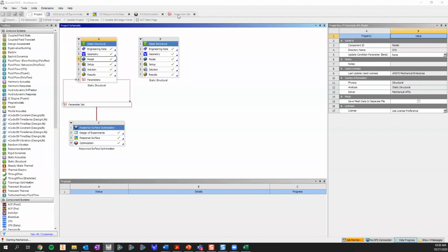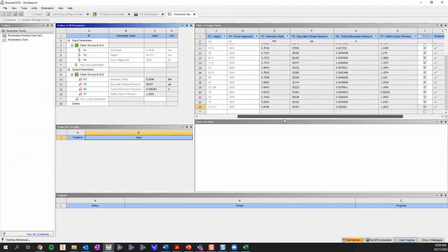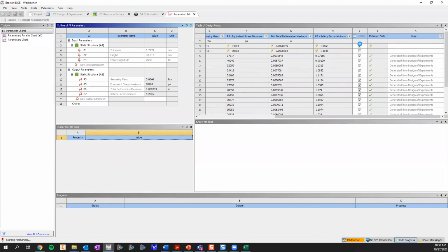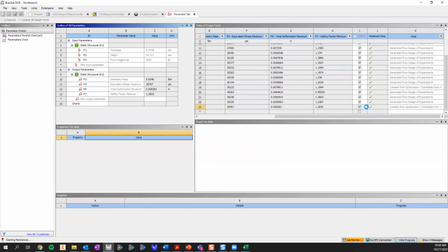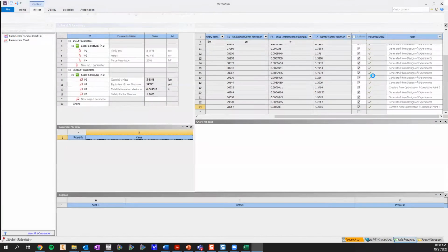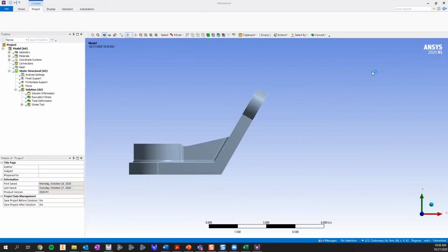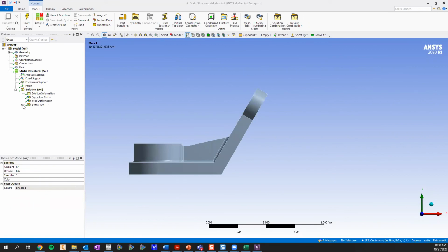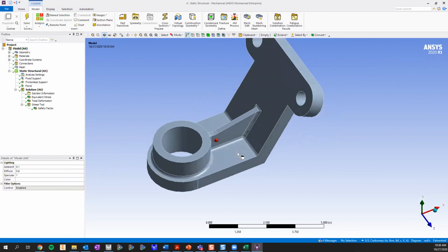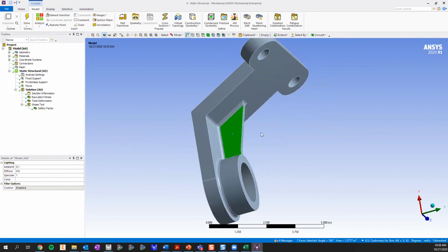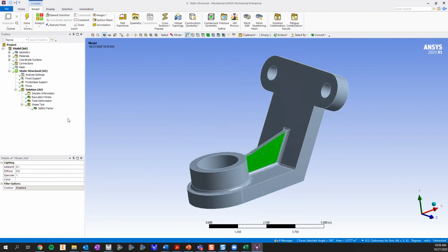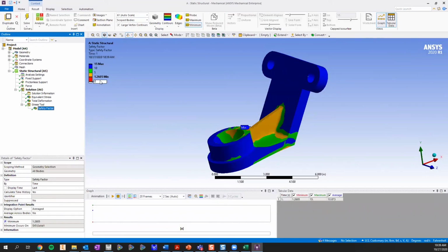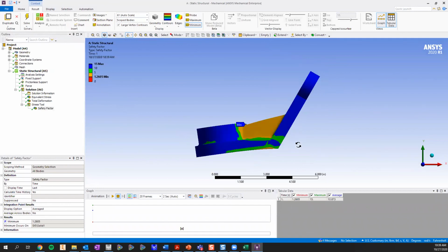Oh, you know what? There's a step I skipped. Let me go back to that. If you click over here and you retain the data, then when you save it, it's going to save those all as simulations that are completed. So when you set them as current, it'll do this. And here in our simulation, we can see that it has selected that thickness from the design experiments and that height. And it's giving us a 1.2 factor of safety, which is a bit better than what the statistics showed because it had a 1.19 factor of safety.